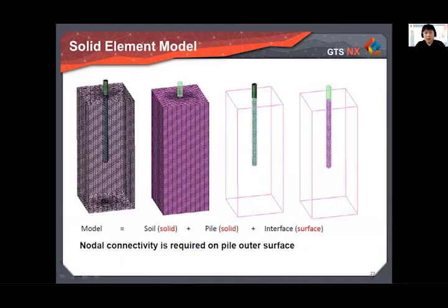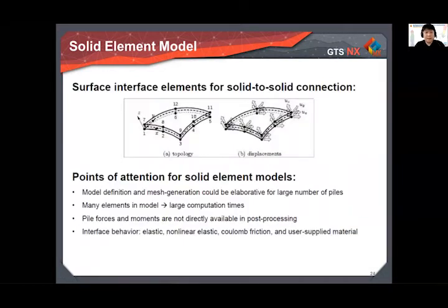So this slide shows the typical solid element for the pile. You can see the solid for soil and the pile, and you can also consider the interface between the pile and soil. But please keep in mind that nodal connectivity is required on the pile surface.